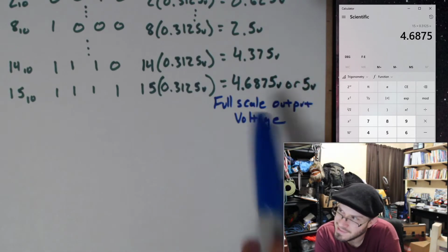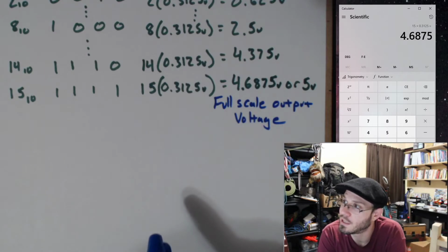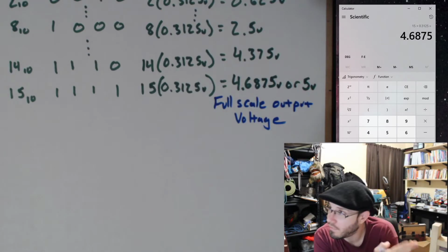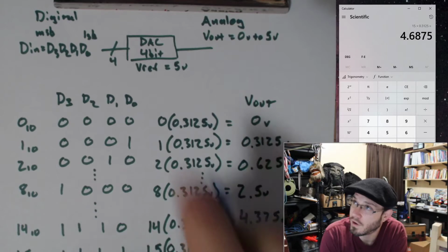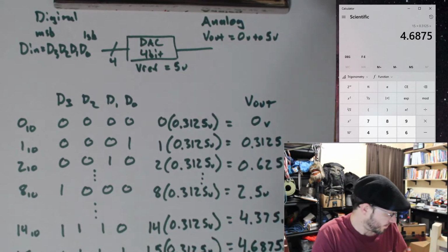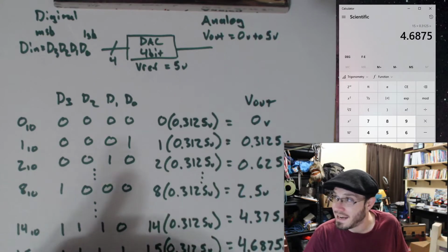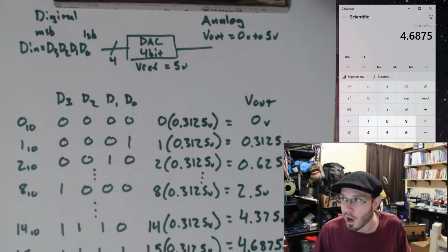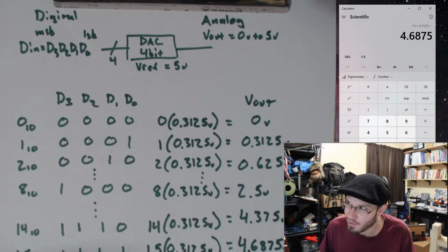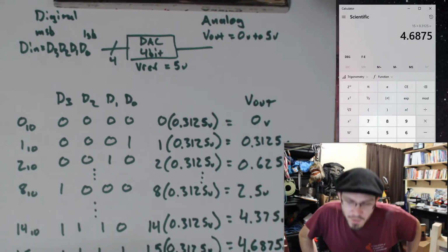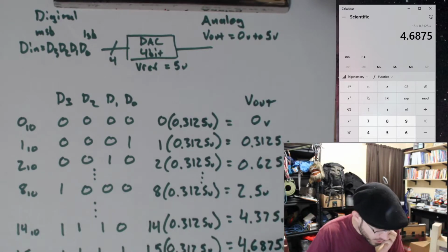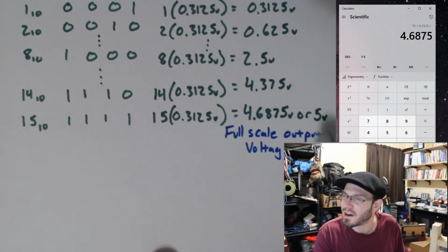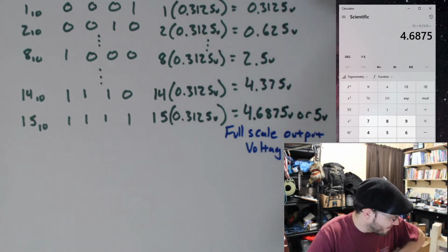Now, again, it depends on the implementation of your digital to analog converter. I'm going to cover in this class 2 different versions of this digital to analog converter. I'm going to cover what's referred to as a binary weighted averaging digital to analog converter, as well as an R2R ladder digital to analog converter. We'll see those in a minute. Okay, and you'll see the difference between this last output over here and how it affects that.